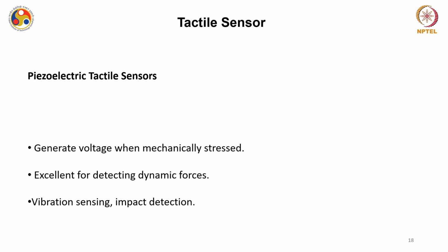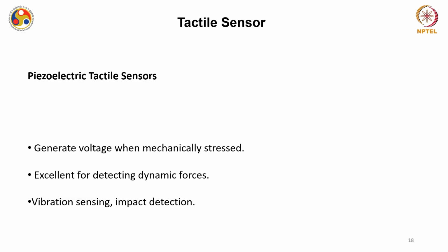If you recall, we discussed that these piezoelectric force sensors are the basic building block behind piezoelectric accelerometers, because they have a natural tendency to measure dynamic forces, and they are not that accurate for static force measurement. Similarly, these piezoelectric tactile sensors are excellent devices for detecting dynamic forces, and you will find that mostly vibration sensing and impact detection applications utilize them.